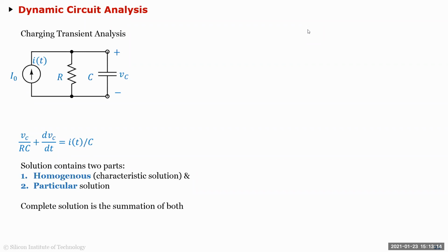And your output impedance is not 0, it's 10 ohms, so just put a 10 ohm resistor in series, right? Then your frequency response is ideally flat from 0 hertz to terahertz or whatever, but in reality you're going to fall off after some time. So you can apply an RC filter at the output to model that. You can just keep modeling like that.